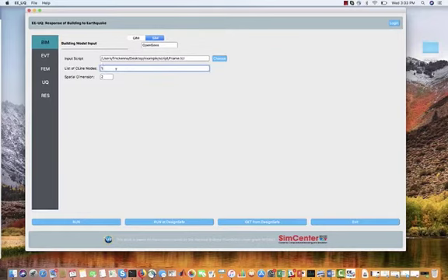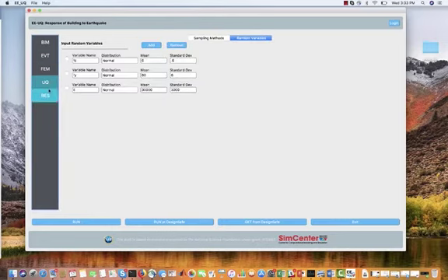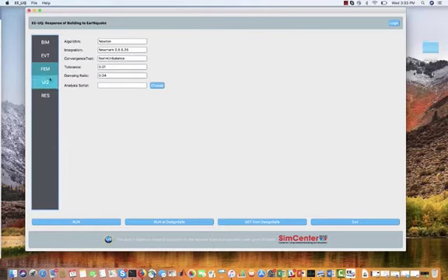For this portal frame, basically there's two nodes that I'm going to specify, nodes 1 and 3. If I had a multi-story building, I might need to specify additional nodes. But right now, as I say, it's a portal frame, so I'm only going to be looking at the responses at nodes 1 and 3. With all that set, I can now run my simulation.